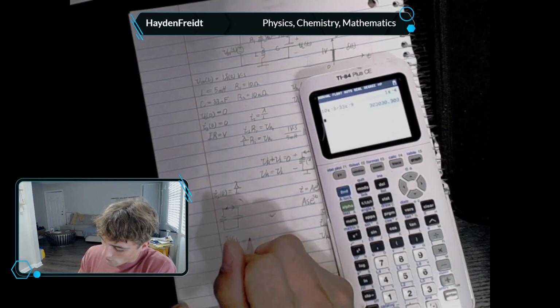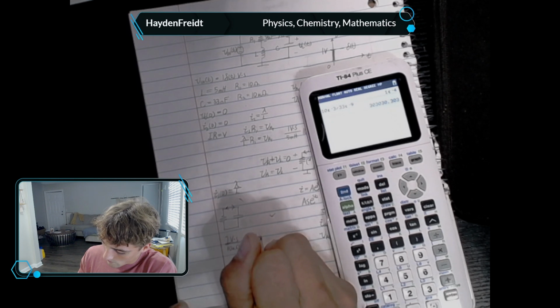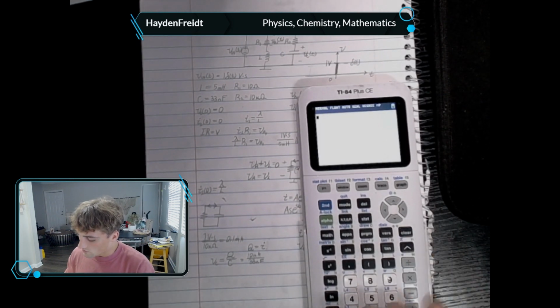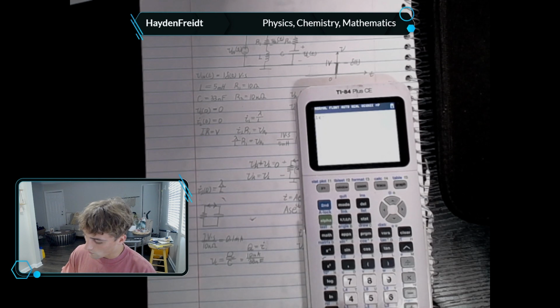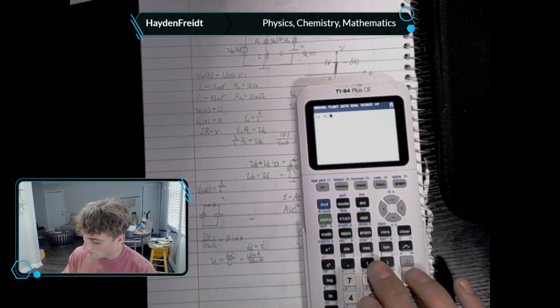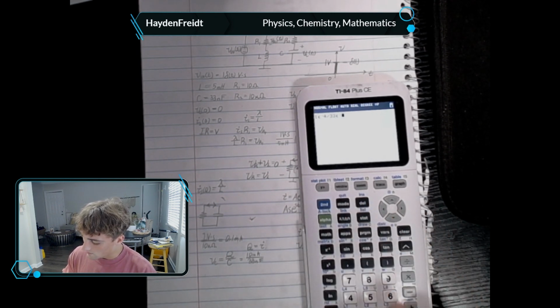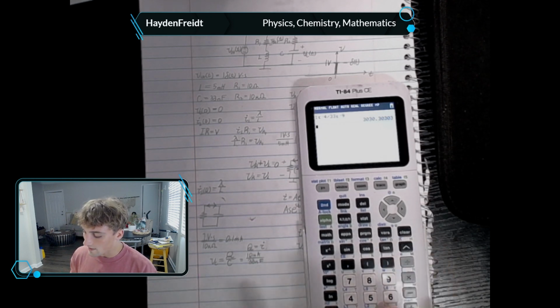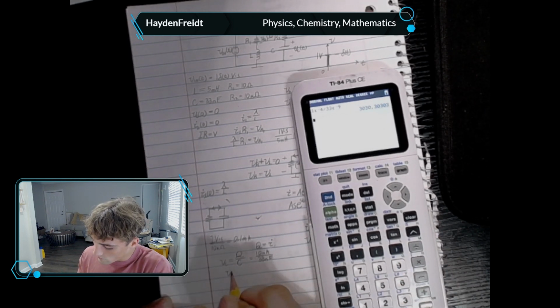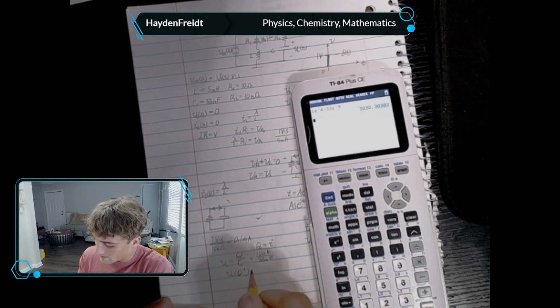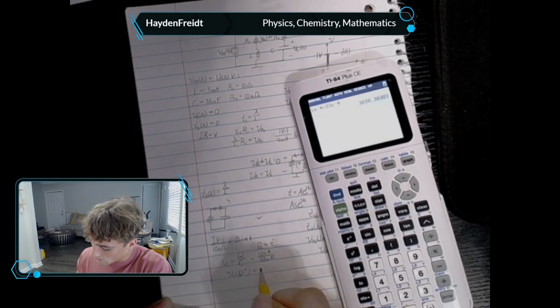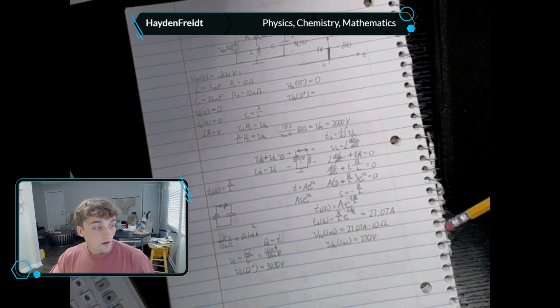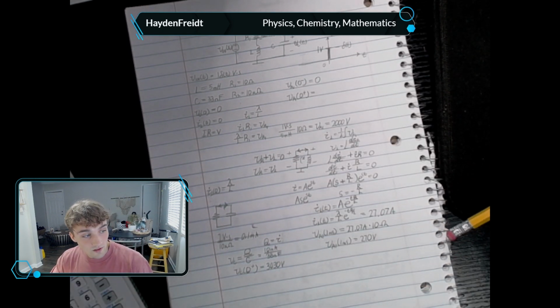It should be 0.1 milliamp. Let's just write it 1 e to the negative 4. That's 0.1 milliamp divided by 33 e to the negative 9. That's our answer. So the voltage across the capacitor a moment after the impulse is 3030 volts. So that's our answer for the voltage across the capacitor at t equals 0 positive, just moments after the impulse had occurred.